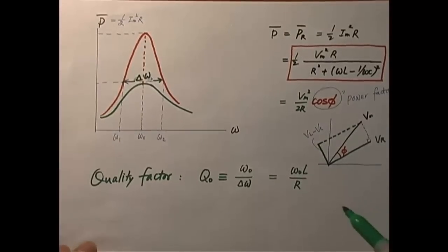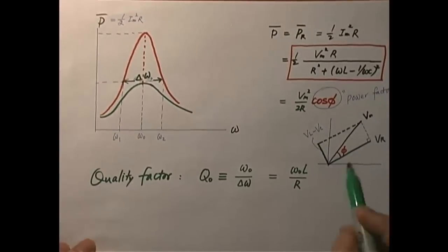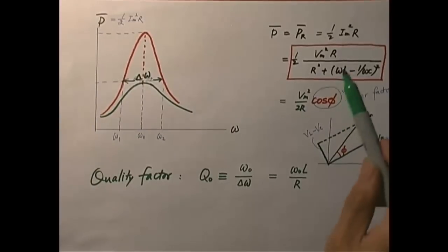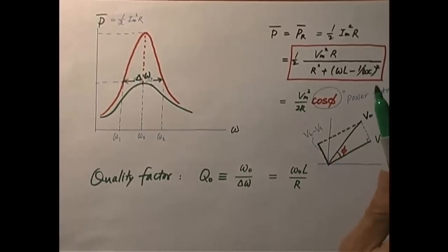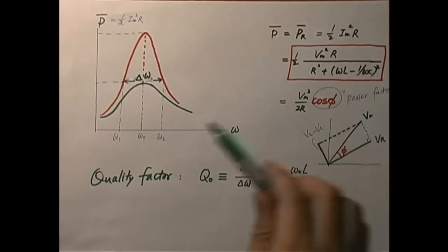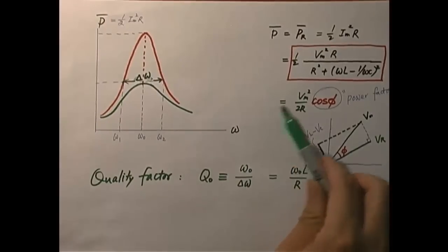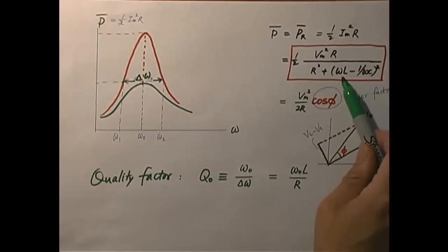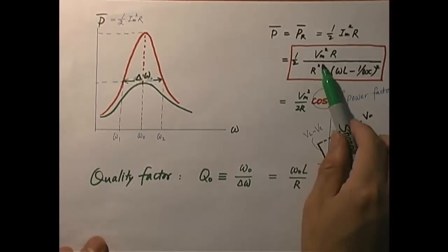And that makes total sense, once again, right? Because when R is equal to 0, the only element that doesn't care about the frequency is gone. You only have L and C. And the system becomes extremely sensitive to the frequency of the driver, and when you drive it at resonance frequency omega naught, remember R is already 0.